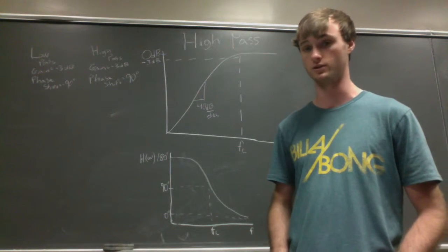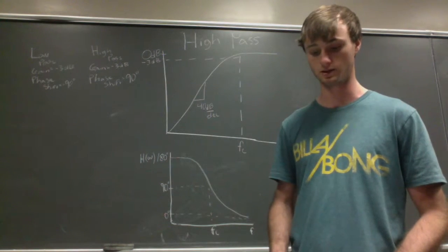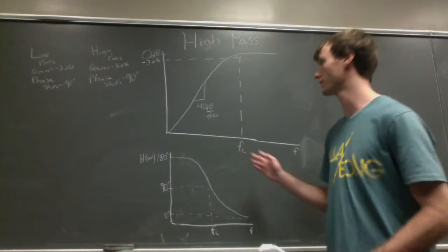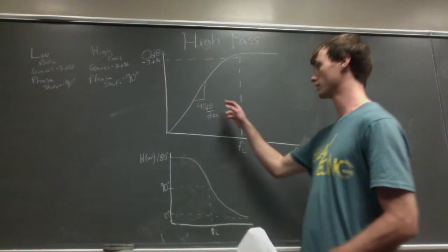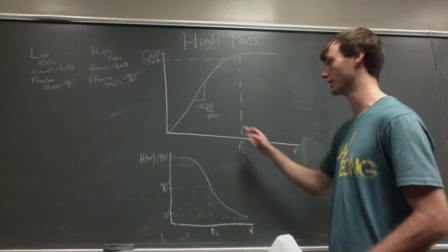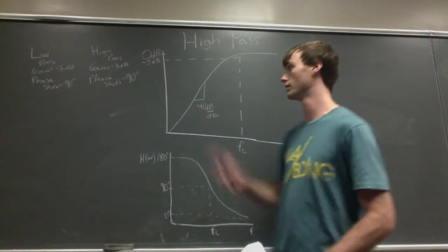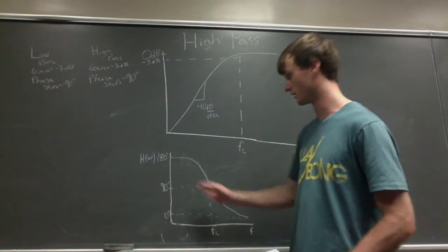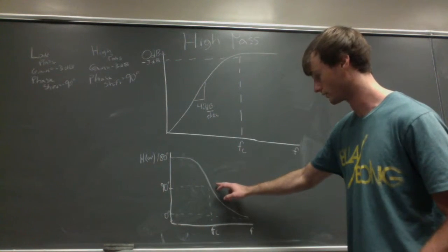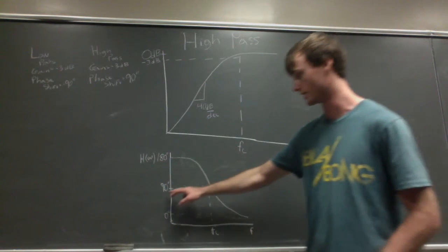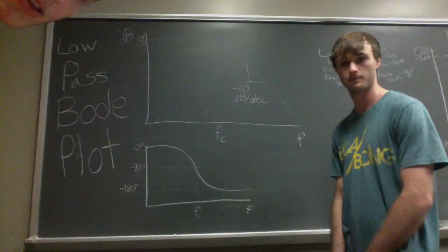The Butterworth filter is a unique filter that's engineered to have a maximally flat frequency response. When observing the high pass second order active Butterworth filter, it's observed to have a 40 dB per decade roll off and to have a gain of -3 dB. Its phase shift starts at positive 180 degrees and its angle cutoff is at 90 degrees and rolls off at 0 degrees.